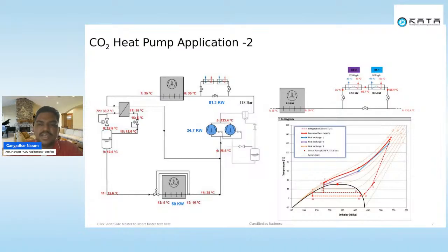considerations, where there is a term called pinch point. We need to understand the pinch point. The pinch point is the point where there is the smallest temperature difference between the primary fluid and the secondary fluid. Here, the primary fluid is the CO2, and the secondary fluid is the water. So where it has the smallest temperature difference,